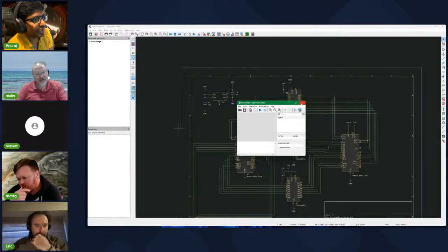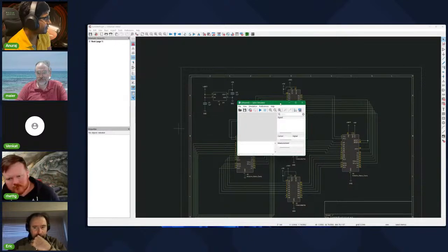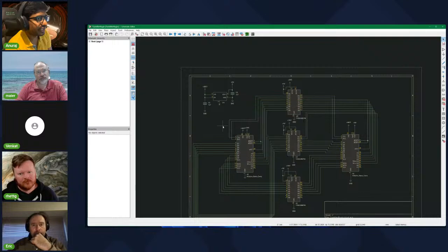Okay. There are different levels of simulation, but in large boards you generally do some simulation because there are so many components. It's hard to keep track of what is happening. So generally you use the SPICE simulator, and I think there is a simulation model you need to import for each and every component, and you will basically be able to click and see if the voltage on that section of the board is correct or not. For large boards, you will do that.